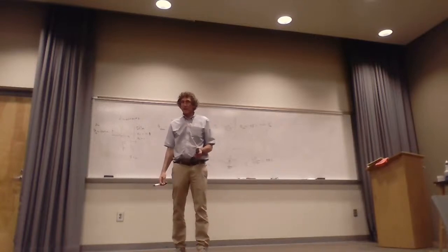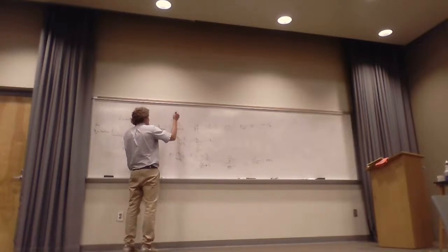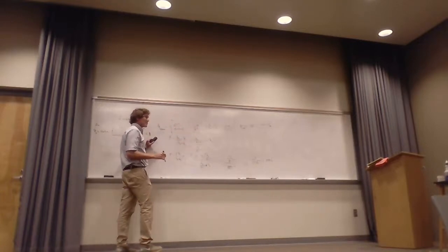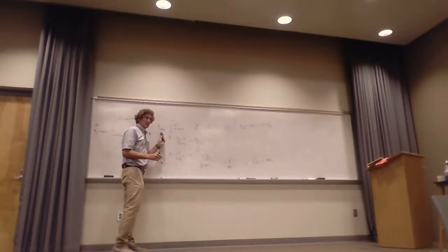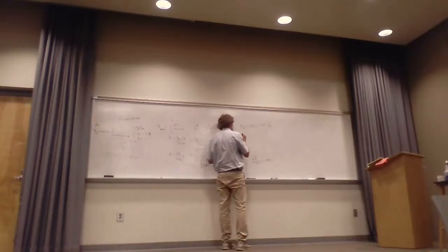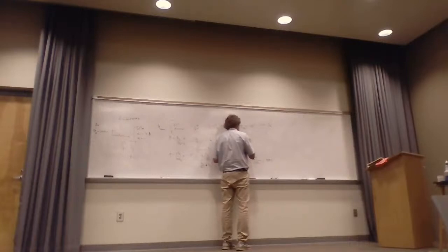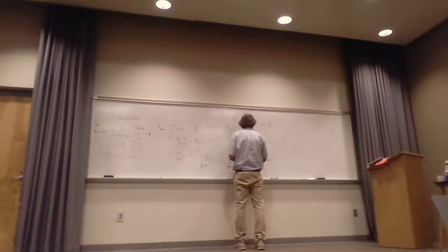All right. Now you want the H field in the Teflon, right? How do we get the H field? What do we need to do? Well, we could write a formal equation, but the real thing we need is eta in the Teflon. The magnitude of the H field in the Teflon, which is most of the time the only thing you care about, is going to be the E field in the Teflon divided by eta in the Teflon.